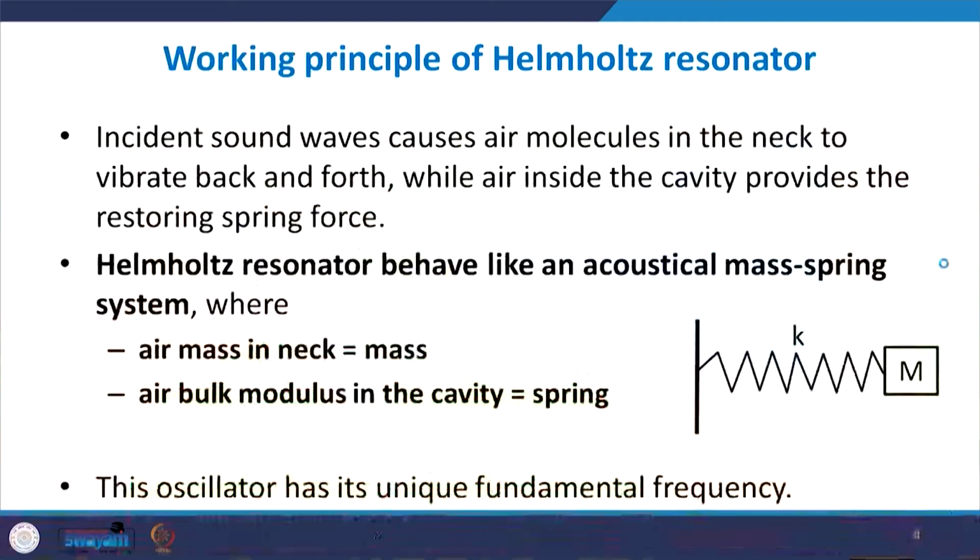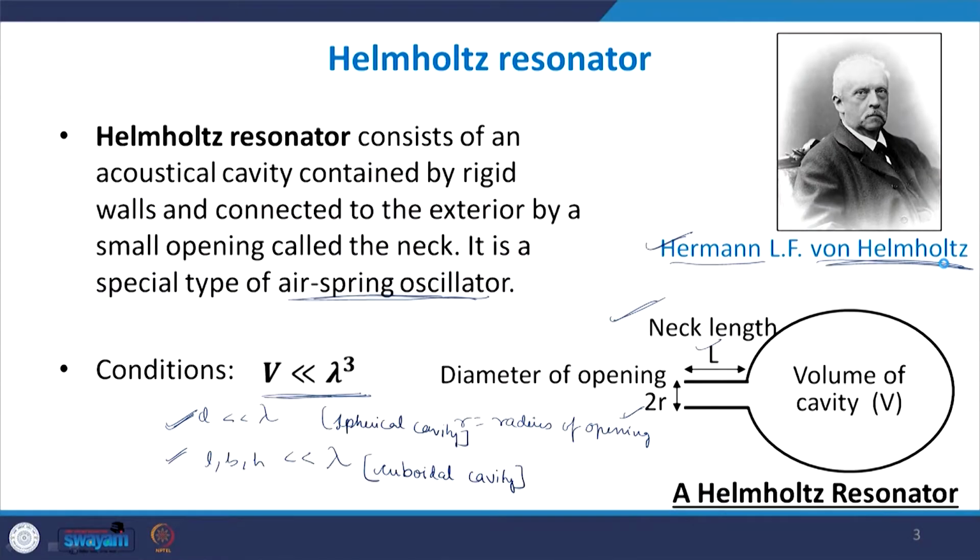So, let us see how this works. Now, here I will again go back to this figure to explain. I had explained to you what acoustic coupling is and how acoustic coupling helps in very high absorption. With the panel resonators we studied that when the frequency of the sound wave matches the natural frequency of the panel, they couple acoustically.